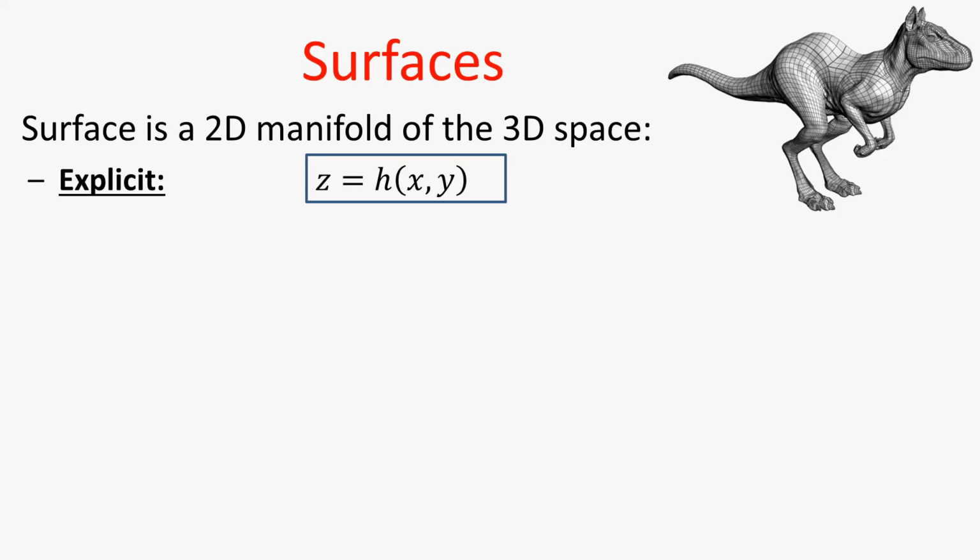One notable exception is terrain modeling, because in maps, this kind of strategy is applied. In a map, we assume the xy plane to be the sea level, and for every xy pair, we specify the height of the terrain at that particular point. With this notation, not even caves can be modeled, and we would also fail to represent a complete sphere with this explicit representation, because for a particular pair of xy values, we would typically have 2 or 0 number of z values.